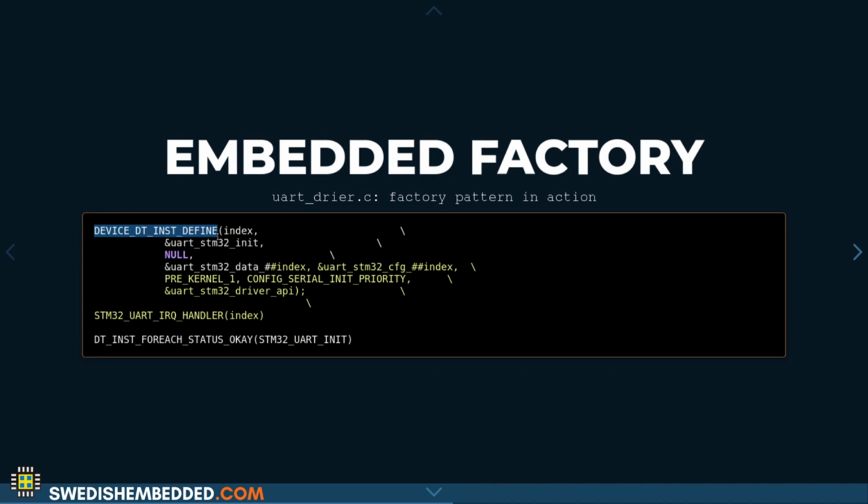In case of C++, C++ will also do this, and it will place a little bit more data into this startup table, where it has the pointer to the object, and it has the constructor for that object that needs to be called. And then the startup code is going to call all of these constructors. And if you've ever used C++ on bare metal systems, you know that you need to do this manually.